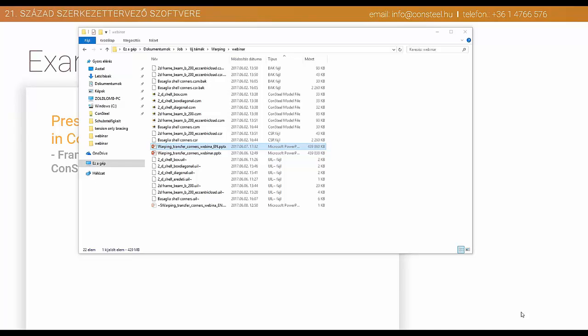It means that if I run the calculations, then the finite elements which fall within the boundary of the corner zone will not be excluded from the different verifications and analyses. As I said at the beginning, ConSteel will consider the bending moments which appear on these elements within the zone, and when one executes a strength or stability calculation, these finite elements will be considered like any other finite element which is not within the corner regions.